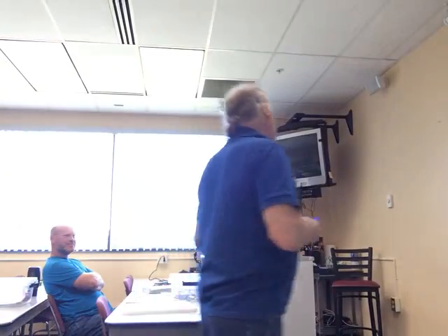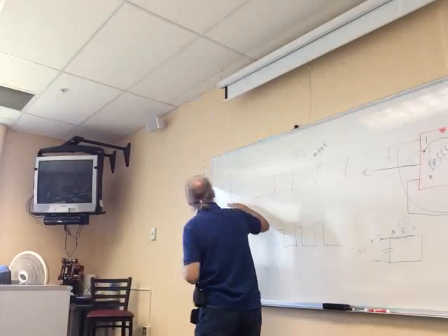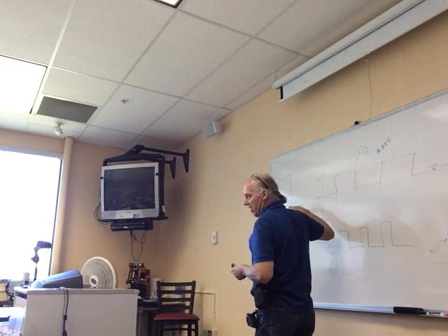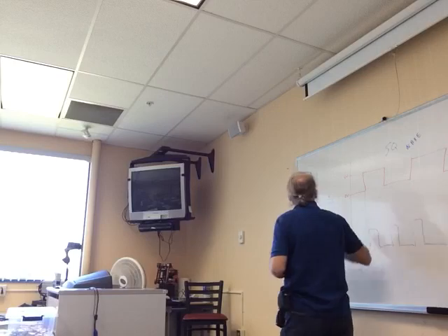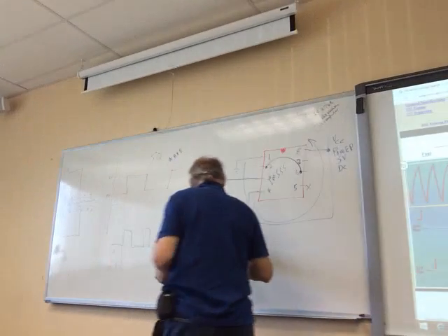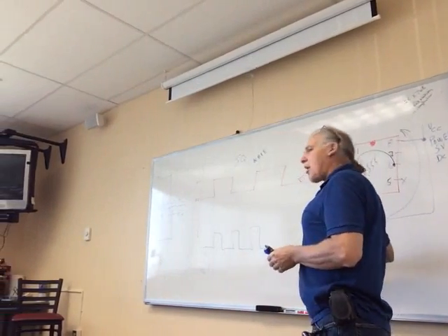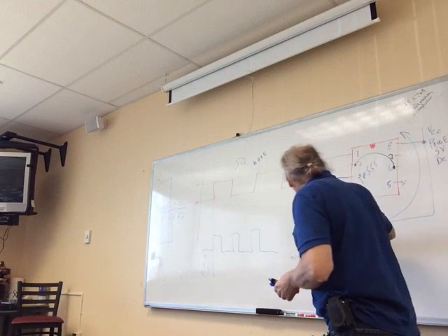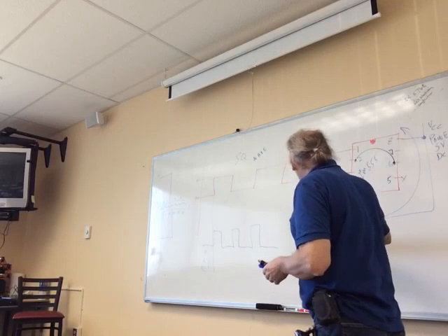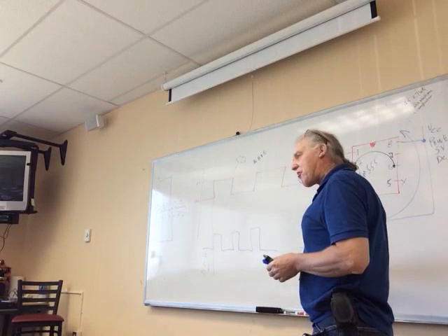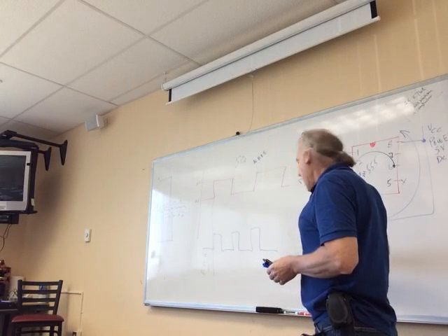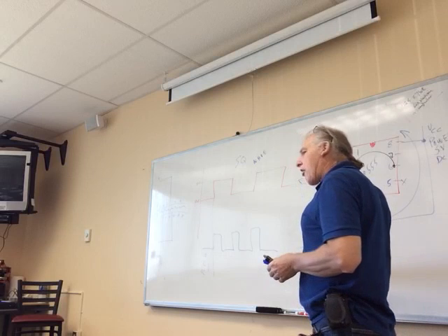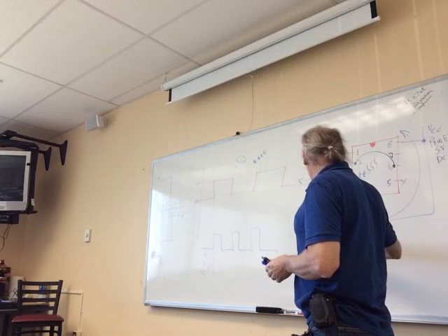But the idea is that the electrons can't get across the insulator. Glass, wax paper, all kinds of different things are used, okay? In our case, we want them to charge up, and then we want to have a resistor. Notice this resistor is in parallel with the capacitor. So the power supply will charge the capacitor. It also will allow some current to run through the resistor.